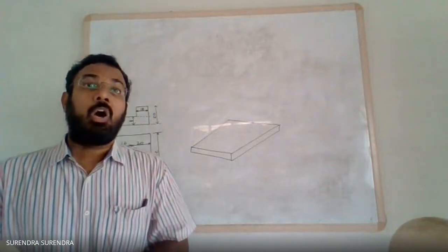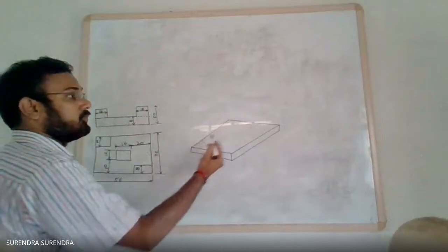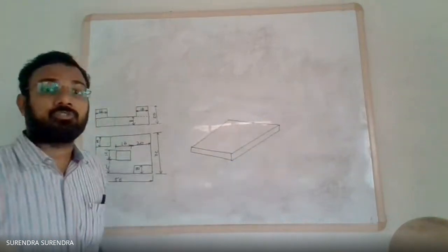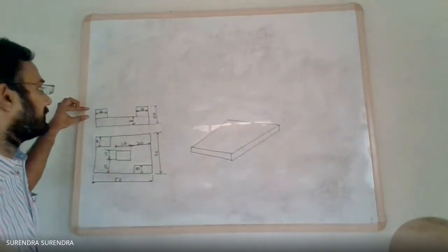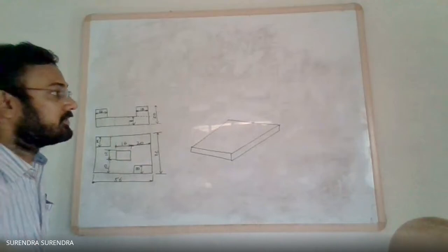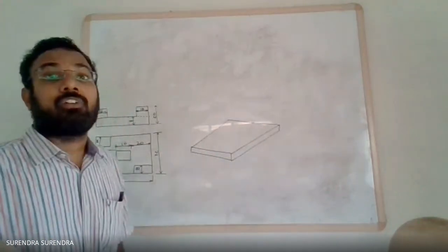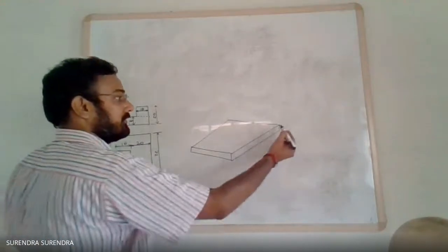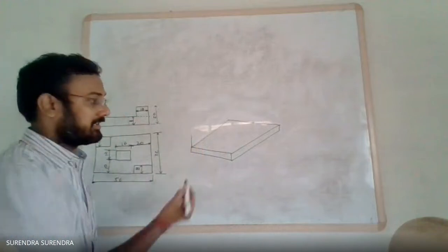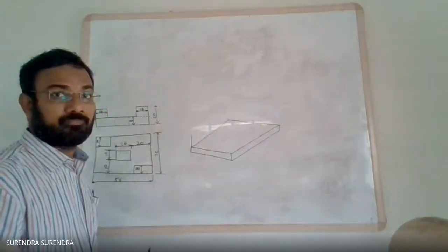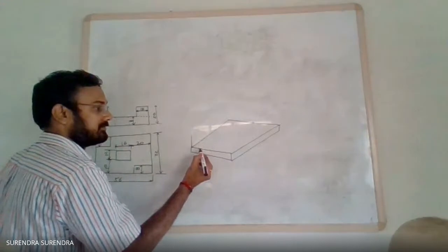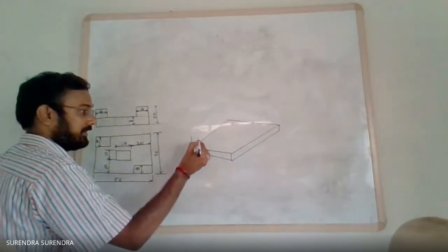Now on this base there are two blocks on the two corners, for a height of total 20 minus 8, so the height is 12 mm. So on each corner there are blocks of 12 mm height. So first let us draw here. From here, 12 mm height vertical, that is, extend this same line 12 more mm. Now what is this width? 8 mm. So from here 8 mm width. Take your point and draw one more 12 mm line.